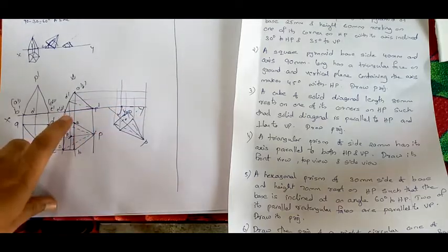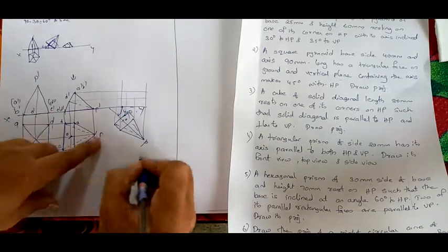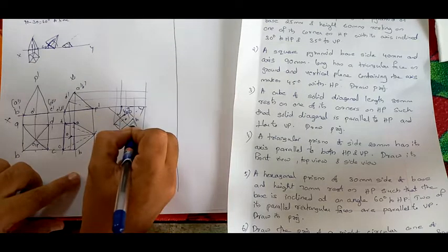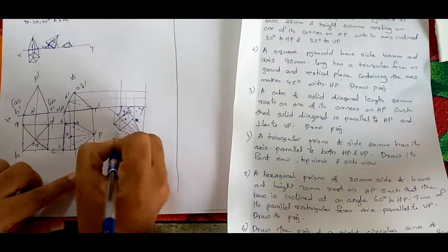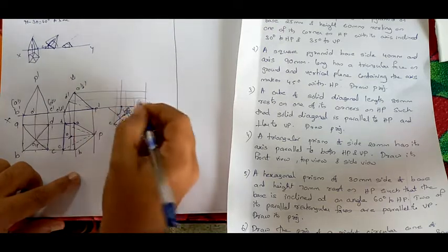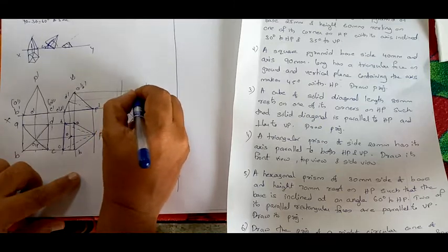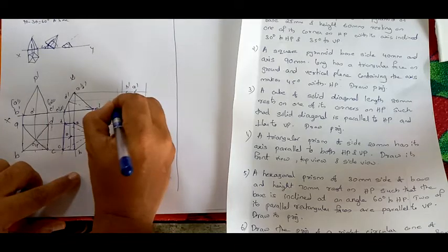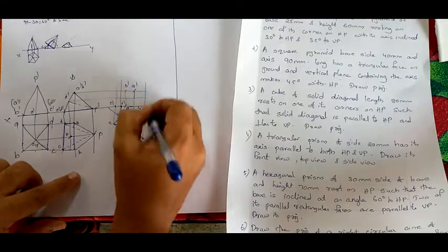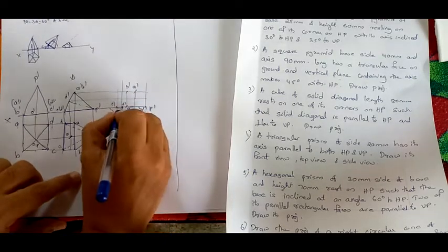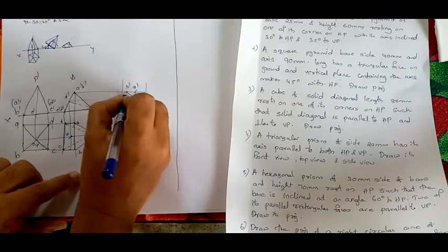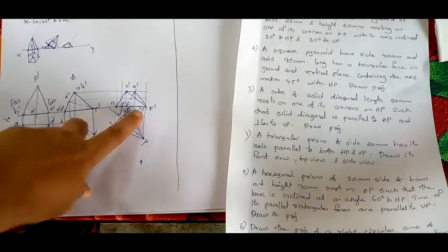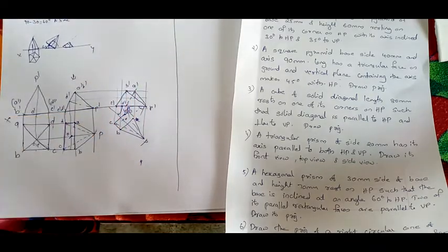If you are obtaining it, you will get it like this. Here basically the base is not visible, the apex is near to you, the base is not visible. So if you are rotating, this will be A, B, C, D in such a way that A dash, B dash, C dash, D dash and P dash. So the base is not visible, so you will get it like this. The largest face will be visible, then this will also be visible, this will not be visible. See, this will be on the same line, only one dotted line will be there, you will get a figure like this, right?